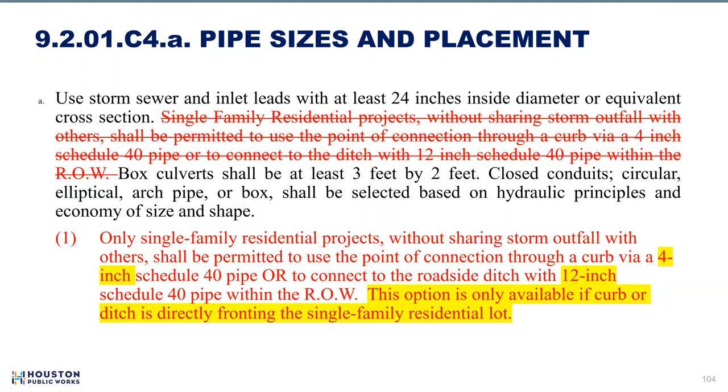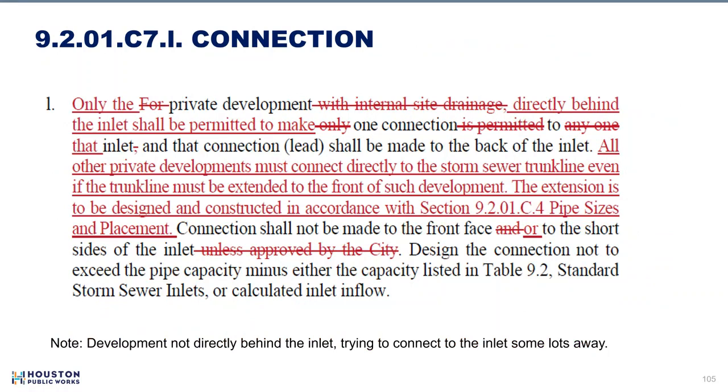This is only for single family residential that is right in front of the curb or the ditches. In front of them, you can do that. Now, if you say, but my development is outside, not in front of this curb, and we'll have to go outside and then inside, set it in the backside, or go through other people's property and then go to a ditch, you will not be able to do that. And this is also not for commercial or shared driveway, PAE, PUE, or access road to use this type of connection.